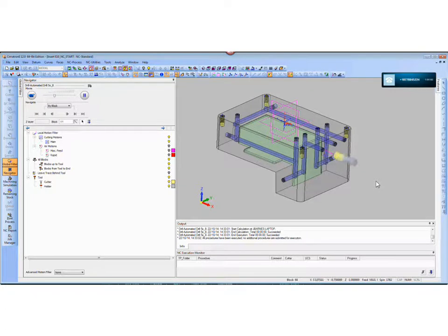So we can set a range and say whenever you encounter a hole from 421 to 422, this is how we want to process that hole. So it's not automatic programming where it has to fit the exact diameter and be processed this exact way. It's more like we define a geometric range and say this is the process that we want to use based on it fitting within this range of geometry.